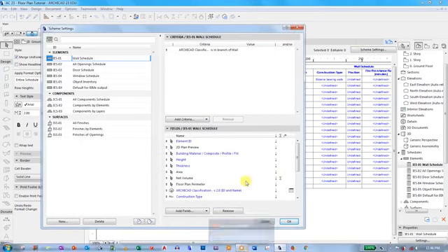see is it prompts me to save this as a wall schedule, and I'll be saving it as an interactive schedule scheme, which is an XML file. So if I click on save, I will have exported this data and it will be stored in the folder called designs, and it will be called IES01 wall schedule.xml. So that's it on how to export schedule data to XML.